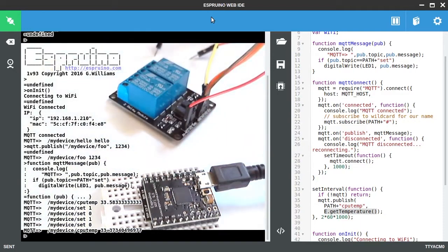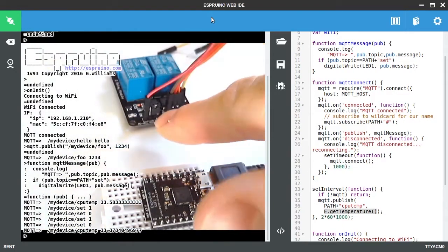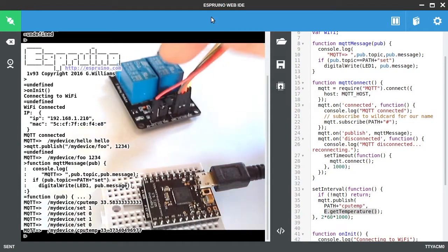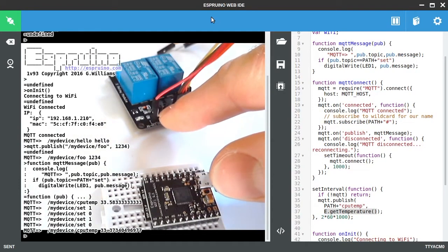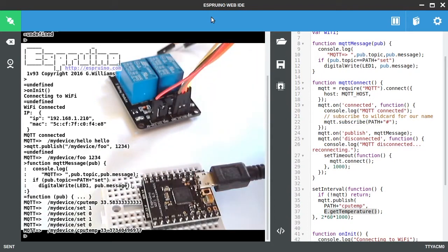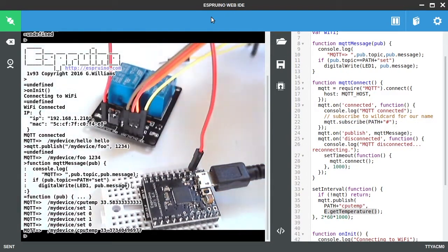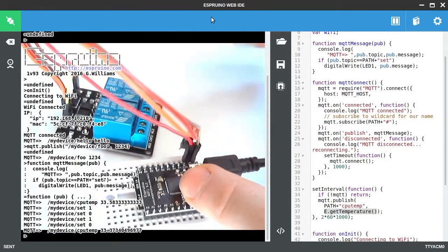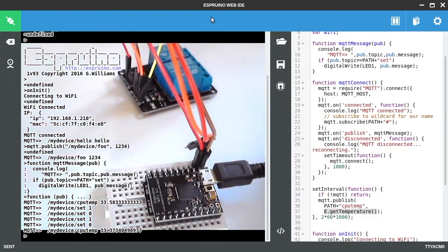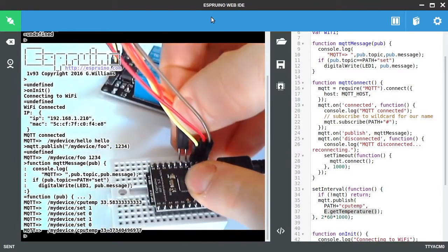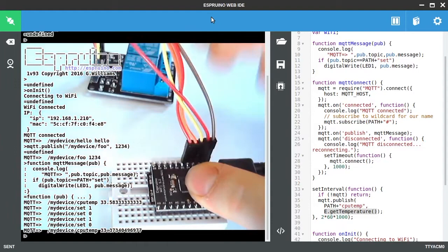To connect this, all we have to do is wire it up quite simply. These usually come with a little plastic jumper connecting JD-VCC, which is the relay's coil voltage, to the VCC that we're actually going to use to activate the coils. Because this is a 3.3 volt microcontroller and this is a 5 volt relay, we want to separate the two. So JD-VCC goes to 5 volts because it's a relay one, and then we just connect up ground, and connect up 3.3 volts to VCC. Finally the 2 data wires, we'll stick those in next door, which are data pins B3 and B4.